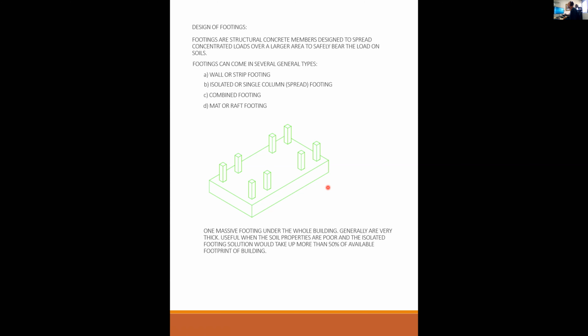And it was designed to carry pretty significant point loads coming down from the building itself. But what was interesting is not only was that mat foundation very thick, but they also had to post tension the whole foundation down through all the bay mud into the bedrock way down there, like 100 feet down.